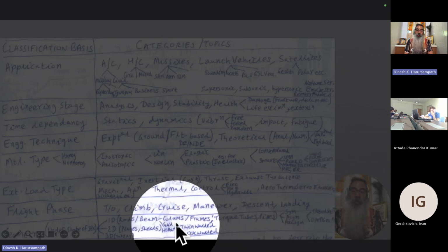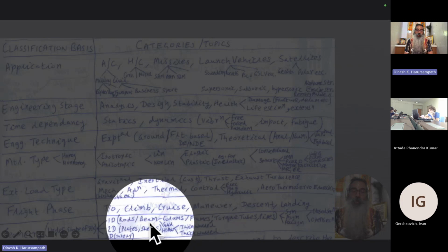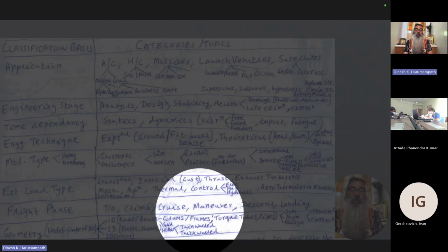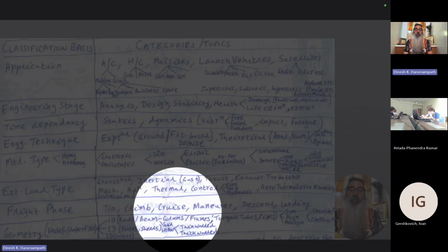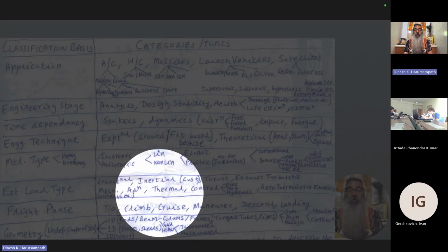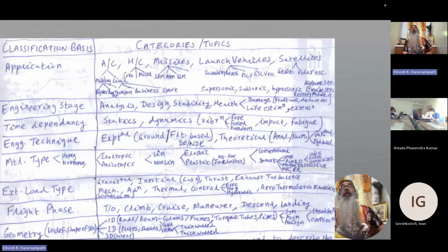And then coming to the beam, we call it the beam, but in most literature, when they say beam, they refer to only bending, but we deal with axial loads and torque as well. So when we deal with axial load, depending upon whether it is tension or compression, you might call it the rod or the column respectively. If it's tension, you call it a rod. If it is compression, you call it a column, right?